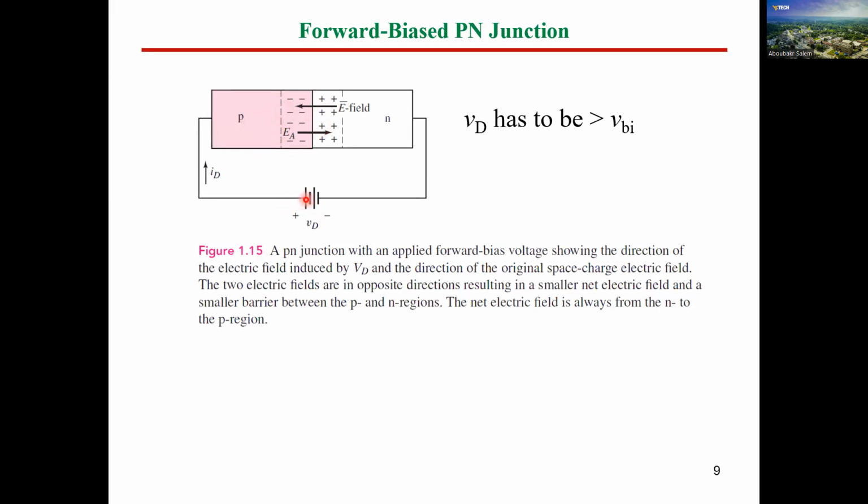The positive charge of the holes will be the same sign as the positive side here, so it's going to make repulsion for the charges. So the holes are going to be moving to this side, and in the other side here, this is negative. What will happen to the electrons in the N material? It will also make repulsion, so the electrons are going to move to this side.